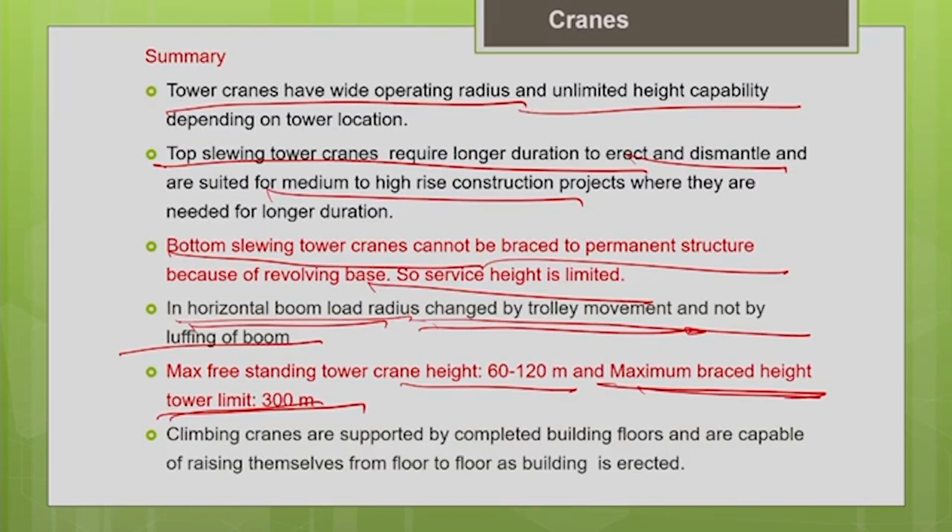And we discussed the climbing tower cranes. Particularly for structures which are beyond 300 meter, we can go for the option of climbing tower cranes. They are supported by the completed building floors. As your structure grows, your tower crane will also grow with the structure. That is why when you design the floor of the structure, you have to take into account the weight of the crane and the load it is going to carry. They are capable of raising themselves from floor to floor as the building is erected.